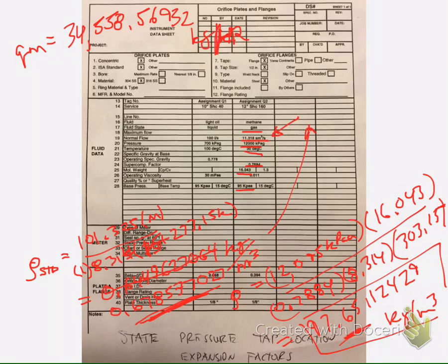So I'm keying these all in. Normally I would probably try to store them in alphanumeric characters, but we got those keyed in now. And the line pressure it's asking me for now in absolute, and that was given right down here. So this is 12,095 kPa absolute.